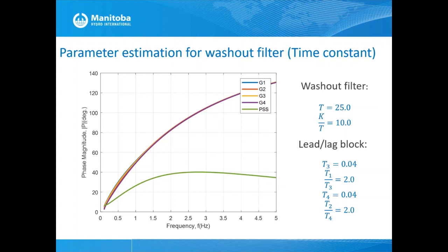A typical known situation is that if you improperly tune stabilizers, it might create torsional issues in the higher frequency range. So you might see some torsional interactions, or it might have situations, I haven't seen those, where it negatively impacts SSCI control interactions. Typically, for a generator that's unlikely because a generator is a huge mass, and the only thing we have seen is that it might impact your torsional oscillations.